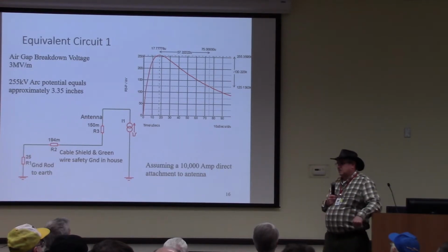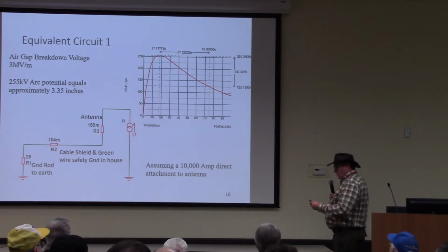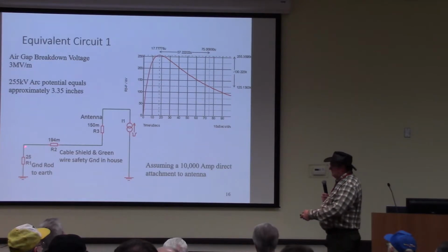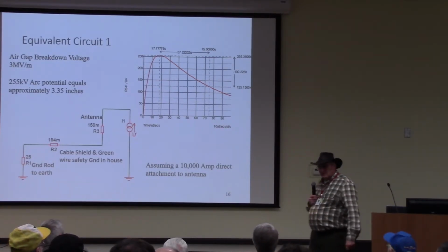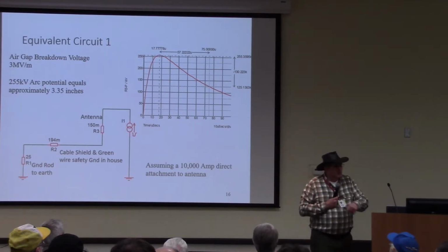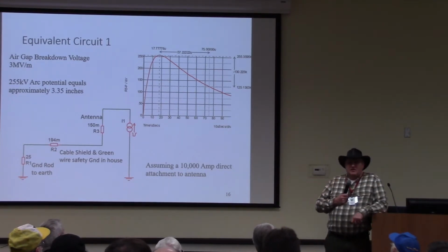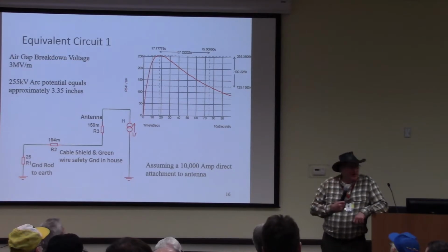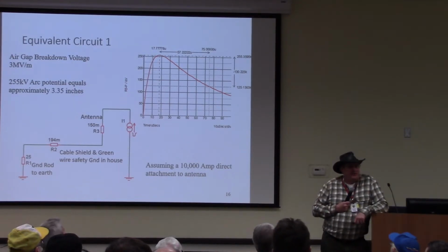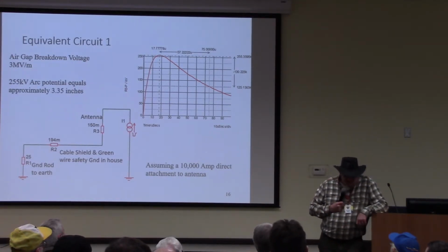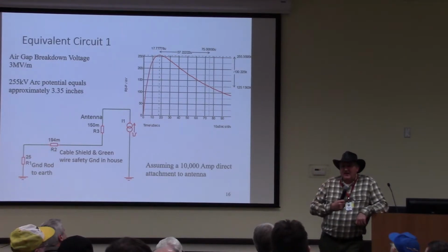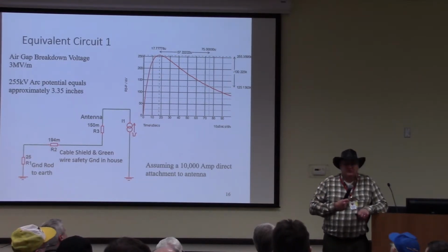Lightning has a lot higher currents. So your house probably has an impedance closer to, worst case, well, actually it can be worse than this, because in a lot of residential installations no measurements are made. They follow the code, take an 8-foot rod, pound it into the ground. It's typically a 1/2-inch rod, and that's it. They meet code, done.